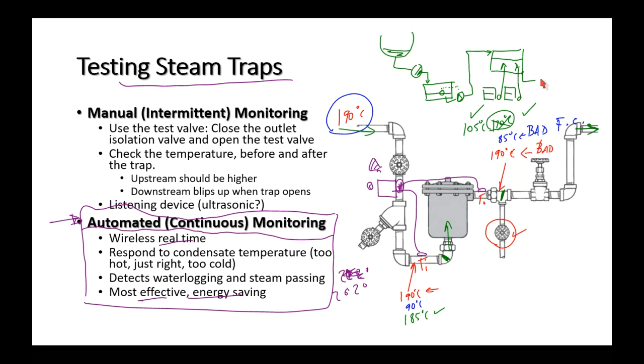Then from the condensate tank, the main condensate tank will have a condensate transfer pump, usually a few of them. And the job of the transfer pump, you can take the condensate and it's going to put it into the heater compartment of our deaerator.